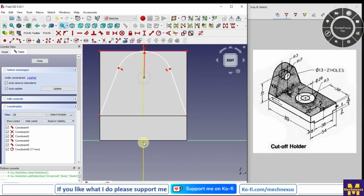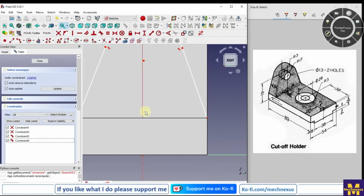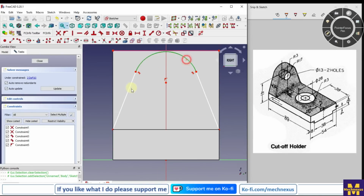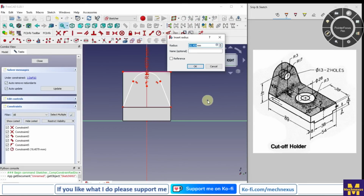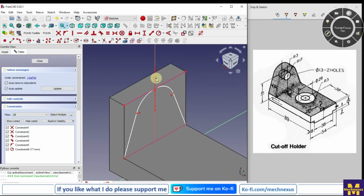Now we can see that this should be vertical. Here is a conflict, so I will delete it. I will make a point and line constraint here. Okay, now I will give my radius 17. Now I will switch to the isometric view and let's see. This profile is not closed, so I will close it. Now we will add a tangency constraint, so now it is fully constrained.